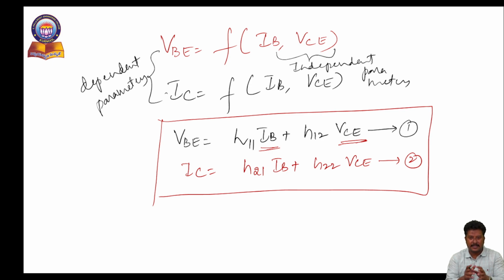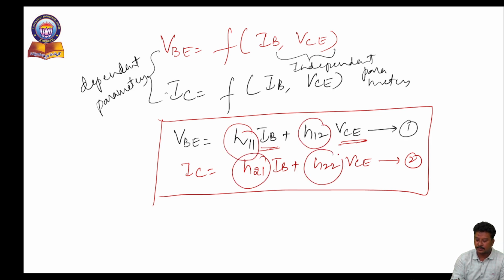It is a little bit easy for us to analyze. Why? Because we can easily apply short circuited and open circuited conditions, and we will try to extract what actually H11 explains, and H12 and H21 as well as H22, and how we have to relate these four parameters to the parameters of the amplifier.